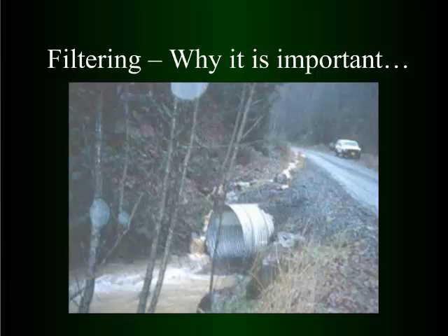Filtering. This is a problem. We'll actually see this today, where you have ditch water coming down and dumping right into a stream. And there's several problems with this. Many times you'll see an example today where it's coming down, dumping into the inlet, and one of the pipes we'll see today is actually fairly well filled in, and it's not from material coming down the stream itself. It's actually from material coming down the ditch line.